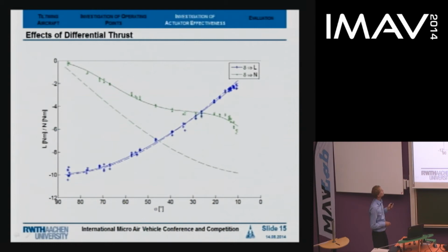And I plotted these two equations in dashed lines here. And I scaled them to the uninfluenced inflow of the main propulsion system in hover. And therefore, we see that we have great deviations between these two. And they might be caused because the inflow of the propellers, of course, changes with higher inflow velocities. And so the main impact can be seen here in yawing, where we have reduced the possible yawing moment in fixed wing flight to approximately 6 Newton meters.